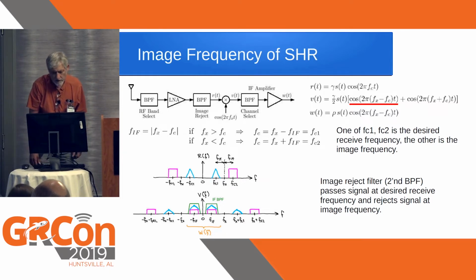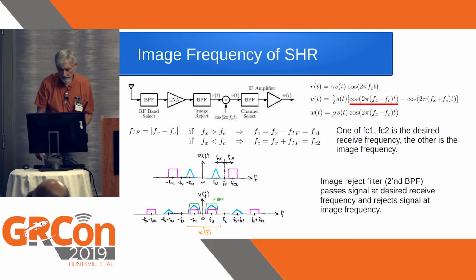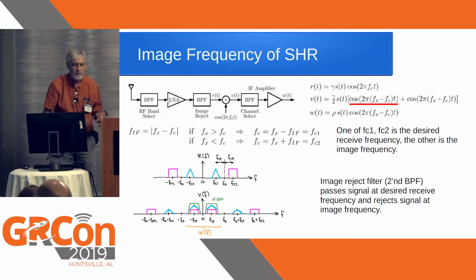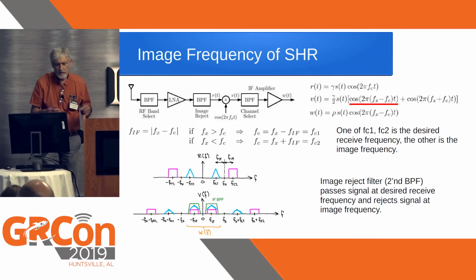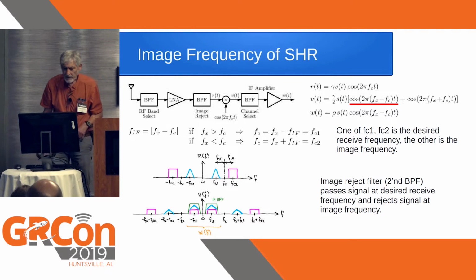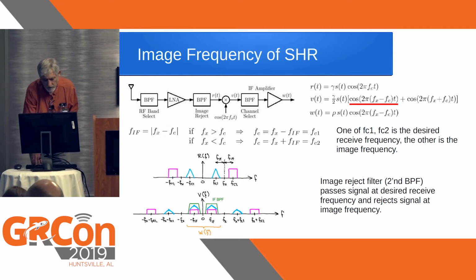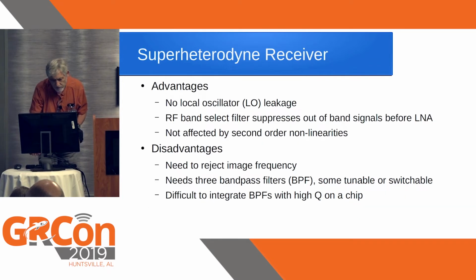Okay, and so that has been a problem in general for superheterodyne receivers, that you need to suppress that, and that actually requires that you have both of those filters here in general, one to protect the input amplifier here, and the other one to actually reject the image. And you cannot, for example, leave out the second one here, because otherwise you get all the noise from the preamplifier from the image channel, even though you don't get a radio signal from that. So that would reduce the noise figure, or actually increase the noise figure of your receiver.